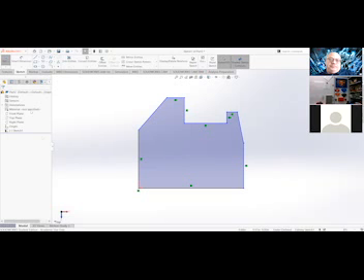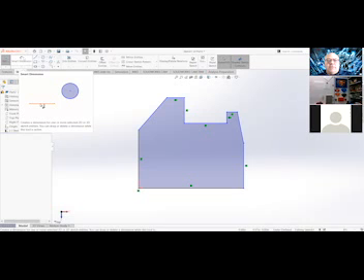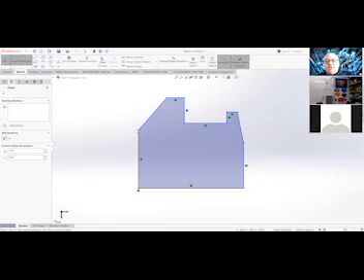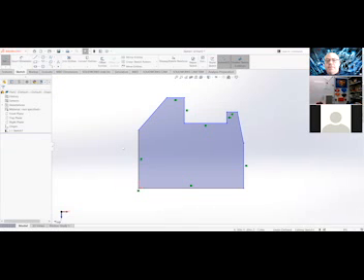It's not any bad. There's a big button that says Smart Dimension, and it works just like the dimension we did in AutoCAD. So go ahead and activate your Smart Dimension, except it's easier. I can pick 1 point, 2 points, and do that. That's boring, so I'm going to escape out of that. You can practice that. If you don't like what you're doing, hit escape. It'll kick you out of the command. Then go back to the command.